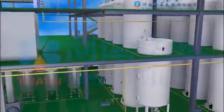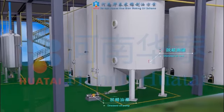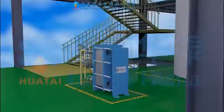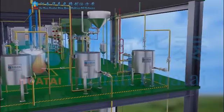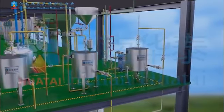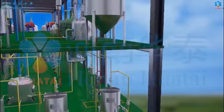Then it is conveyed to the oil plate heat exchanger by the dewaxing oil pump to exchange heat with the dry oil. After that, the oil will be sent to the oil heat exchanger to exchange heat with the deodorization oil, and then goes into the dewaxing oil heater to get heated and temperature-raised.